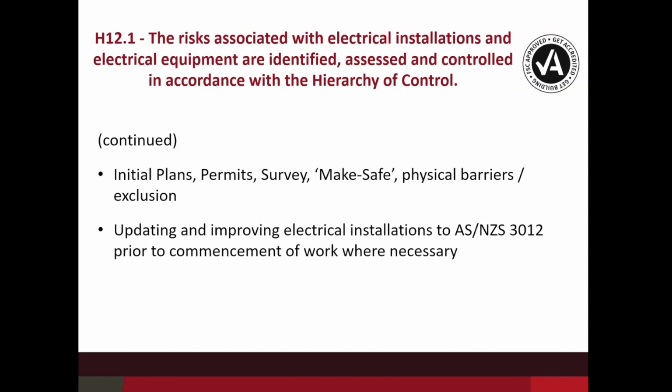The other situation is where we utilise some of the conditions within the premises when we're doing fit out or refurbishments and things like that, and they'll bring it up to standard. Now, we do need to bring all of those up to standard in order to use them for construction practices. So we need to think about, if we've got a really old installation, how do we get that to a point where it's compliant to be used as a construction wiring system.